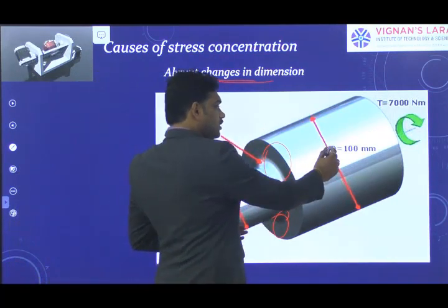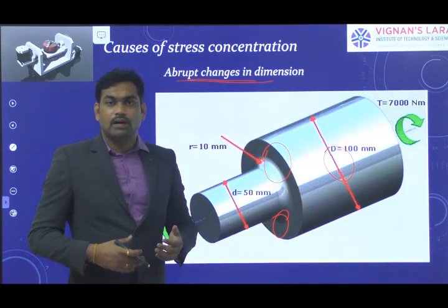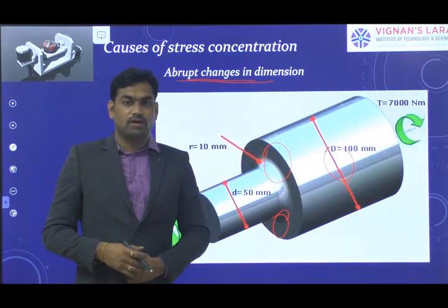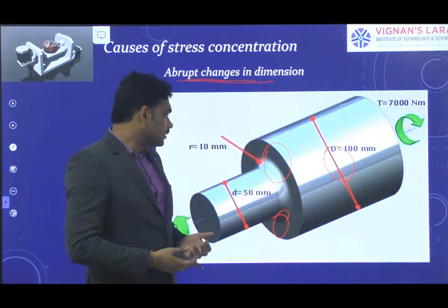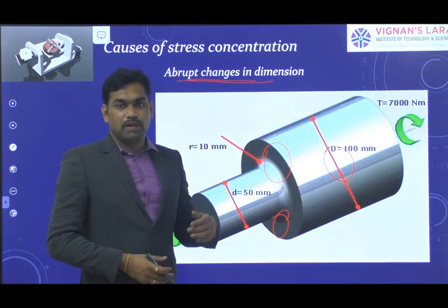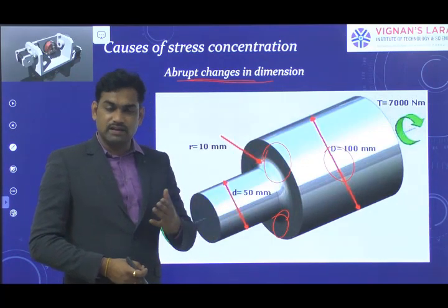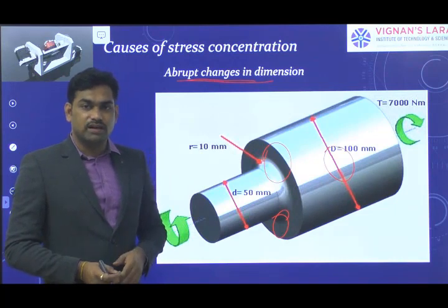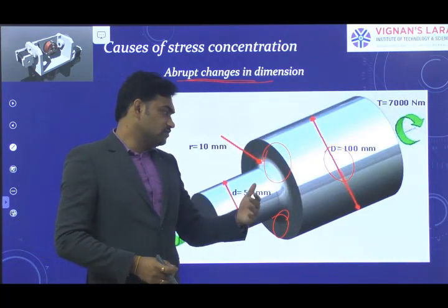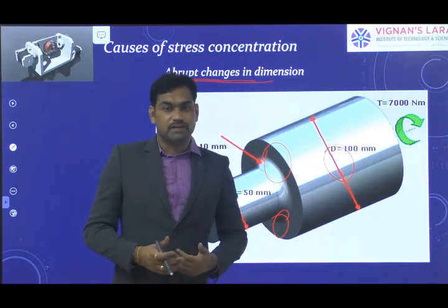If you place a hole here, you can drill a hole, or you can make oil holes, or if you want to create some sudden changes in the cross-sectional area, by placing a groove here or rectangular slots, or whatever you prepare, any sudden change in the cross-sectional area will give rise to increased stress.